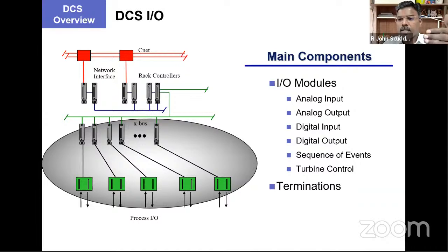And when you get the sequence of event report, it's so interesting to analyze that, okay, this has happened first. This is the root cause, followed by these events, and then this. Finally, maybe if there is a 10 seconds time delay, you will be so interested to see that after 10 seconds of that particular thing happening, exactly the turbine would have tripped. Okay, not in the case of lube oil pressure, but in some other cases where we have 10 seconds of time delay for operation engineers to take control and maybe change the process. So hope you are able to understand.